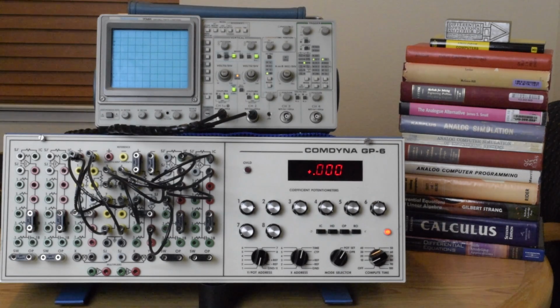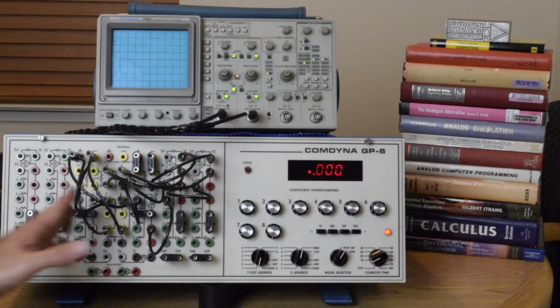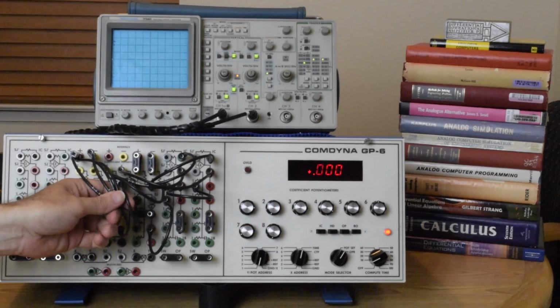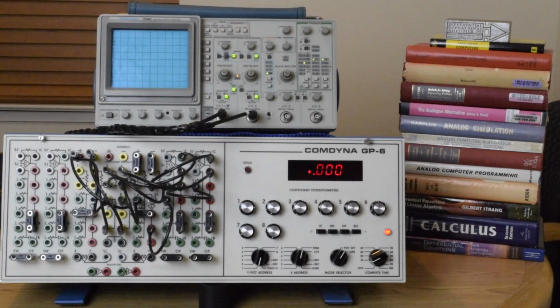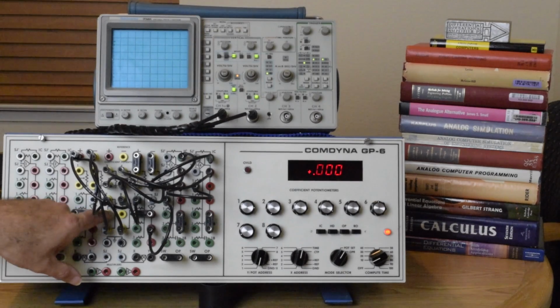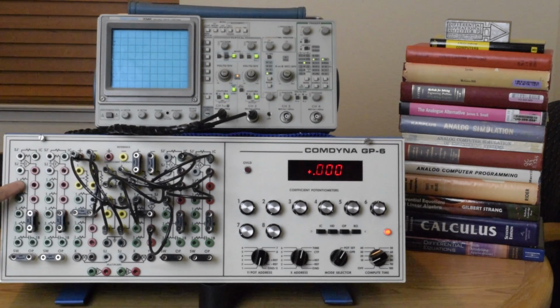So the way we enter that differential equation into the analog computer is we generate the variables of interest, and in this case we have a way to integrate the actual dy/dt equals m directly. So basically we will input the value of potentiometer 7 into this integrator, and it can integrate directly, which is a very useful feature.